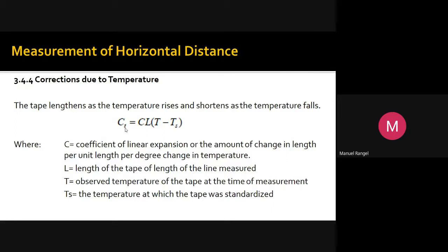So general rule to obtain more accurate measured values, taping should be undertaken when the temperature does not vary significantly from the temperature used during standardization. So, mas maganda kung early morning kanang dili kayo init. Okay, so better results are usually obtained when measurements are made on cloudy days, early in the morning or late in the afternoon. So there may be considerable difference between the temperature of the tape and the air during bright sunny days.